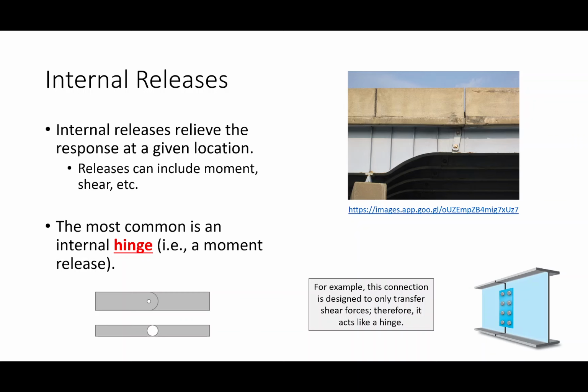You apply a moment to a structure where there is a hinge, it will freely rotate, okay? So our fourth equation: we're going to have sum of forces in the x direction, sum of forces in the y direction, sum of moments about any arbitrary point where the whole structure is 0, but we're also going to have a fourth equation when we have hinges, and that is that the sum of the internal moments at that point is 0.